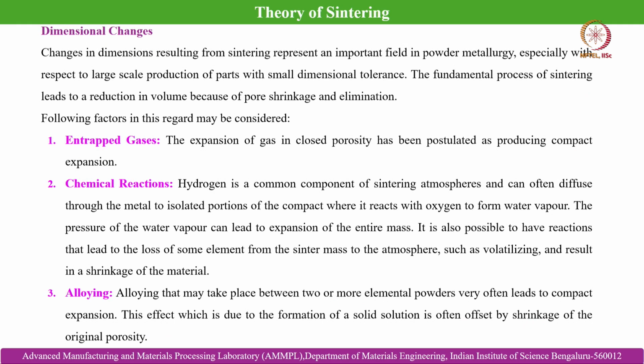The dimensional changes that happen in the sintered specimen. Changes in dimension resulting from sintering represent an important field in powder metallurgy, especially with respect to large scale production of parts with small dimensional tolerance. The fundamental process of sintering leads to a reduction in volume because of pore shrinkage and elimination. So the following factors in this regard may be considered.